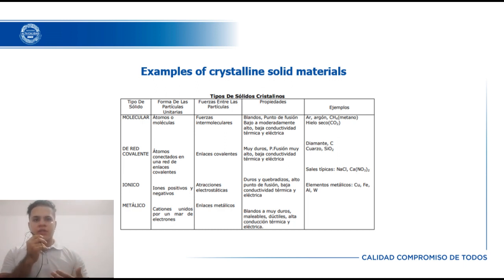The main uses of X-ray diffraction are the following. One, quantitative phase analysis of pure substances and mixtures. The most common method for phase analysis is often called X-ray powder diffraction, or XRPD. Two, analysis of phase changes under special conditions such as temperature, humidity, and applied pressure, and environmental studies. Three, analysis of physical properties such as crystallinity, size, crystal orientation, and residual stress, which together are known as the microstructure of polycrystalline materials.